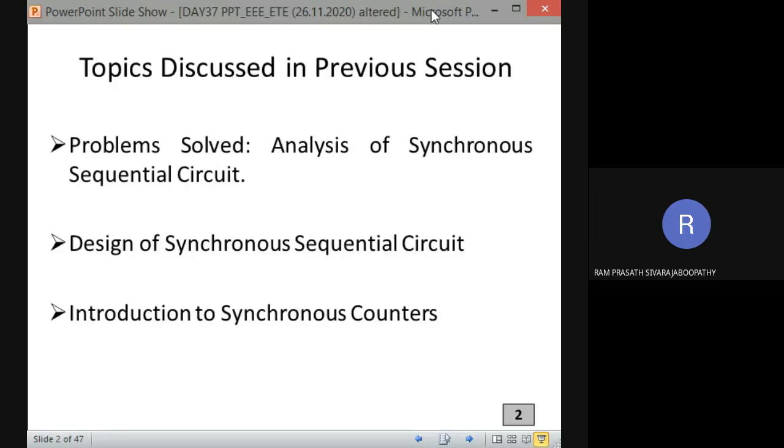Already we have discussed shift counters. That we also call a counter, but there we generated some pattern. For example, with ring counter we generated 0001, and the next state it will shift in ring order, 1000, like that. So it keeps moving from one state to another for each and every clock pulse. In the lab session also we have discussed this.